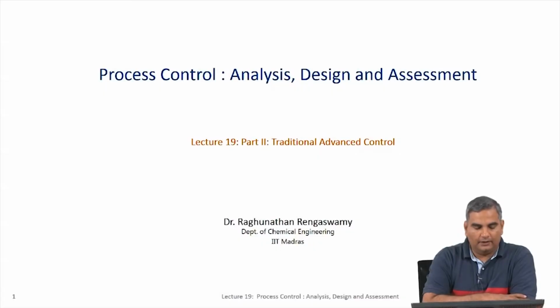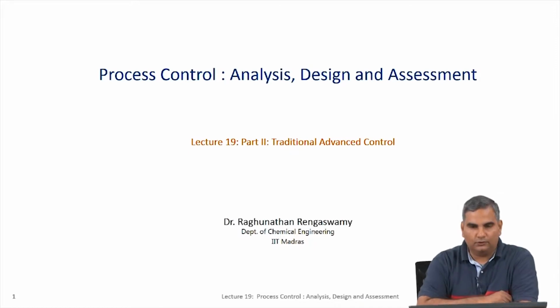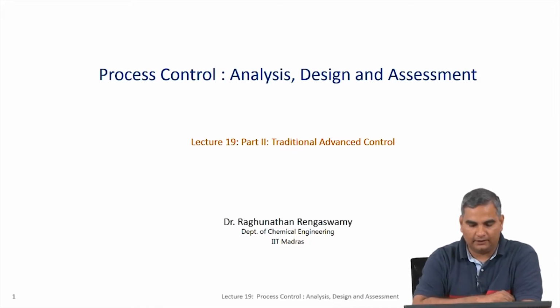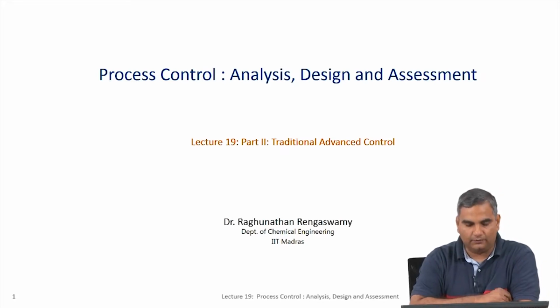Now that we are done with the standard undergraduate control material, we move on to the second part of this course, which talks to more advanced ideas in control, such as control of inverse response systems, control of unstable systems, time delay systems, and so on. And we will also talk about other control structure designs such as feed forward control, cascade control, which basically implement some form of multivariable controller within the single input single output controller framework.